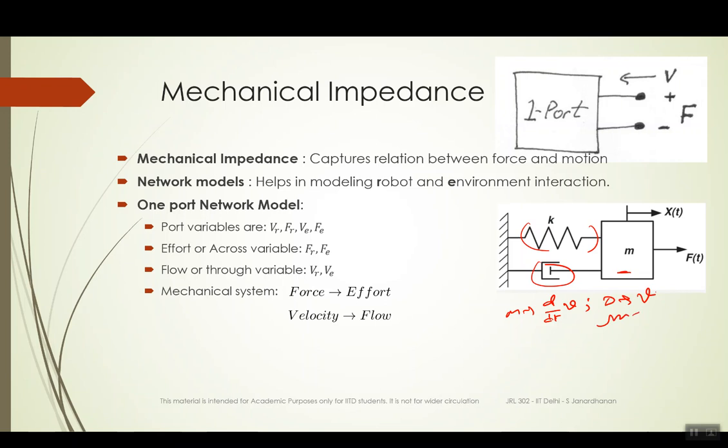And in the case of the spring, the force that a spring will exert depends upon the integral of the velocity. So you have the mass exerting a force proportional to the derivative of the flow variable, the damping to the flow variable itself, and the spring to the integral of the flow variable.